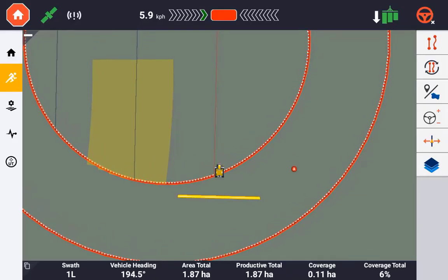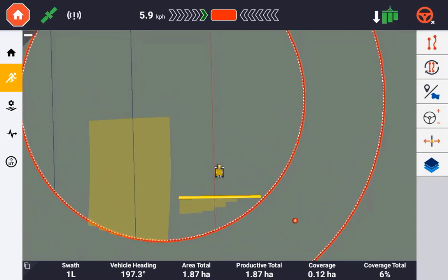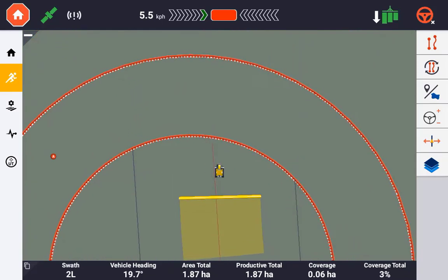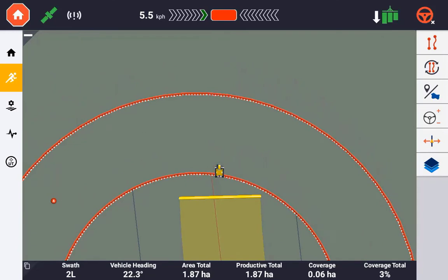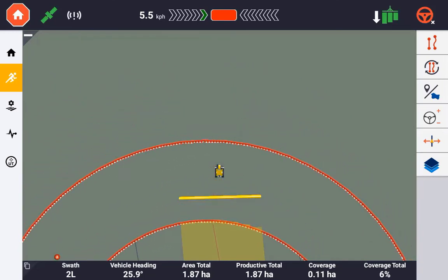It is important to understand that boundary overlap and latencies applied to boundaries is only applicable to when the implement is passing into a boundary area. When the implement exits a boundary area, by default, no overlap or latency is applied.